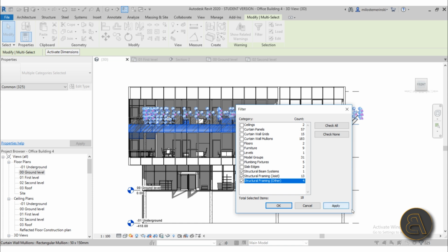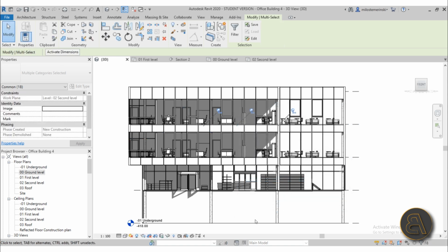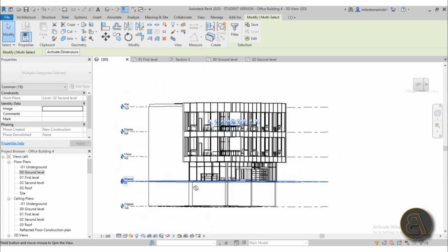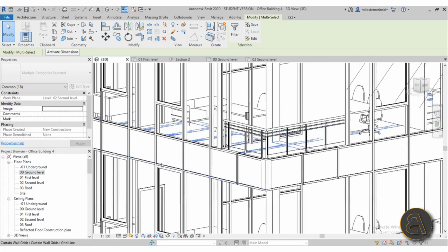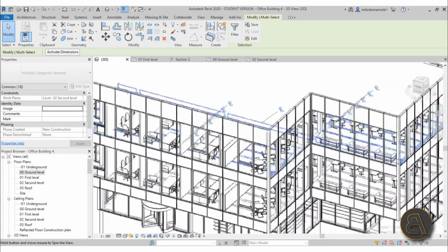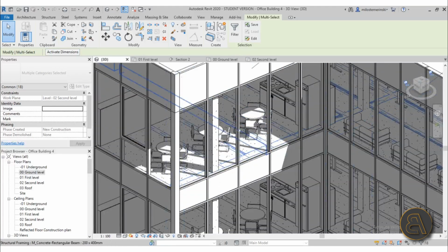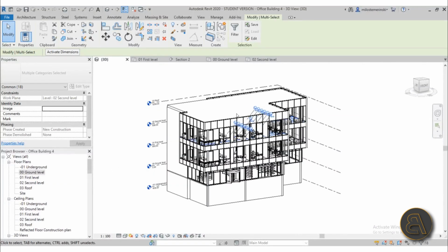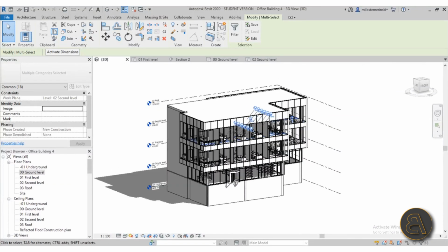Once we have made this selection, or refined the selection to be more precise, we can just hit apply, okay, and as you can see, nothing seems to be selected because it's hidden between the floor and the ceiling. But if you orbit around on top, we have the whole beam system selected over here. Once this is all selected, go here to copy.